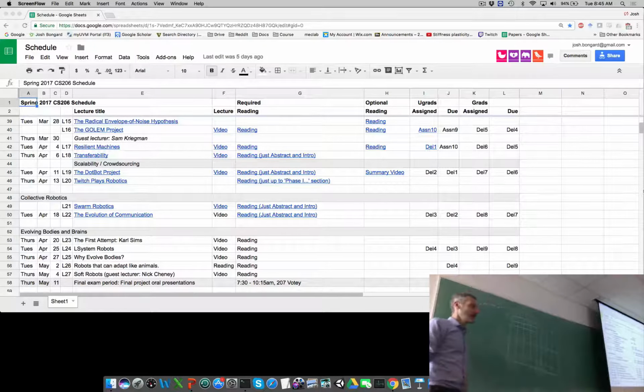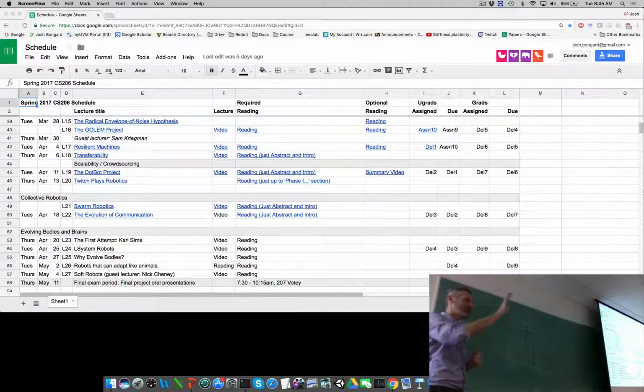You could reward robots for having the count of all zeros being close to the count of all ones. Exactly, right? We could maximize the number of rows like this and then minimize the difference between the number of rows that are all zeros and all ones. That may or may not produce hopping. There may be some other perverse instantiation of that, but that's sort of what we're looking for in the final project, right? You tried fitness function version 1.0, it didn't work. Based on what you saw, you added a term to the fitness function to select against it.